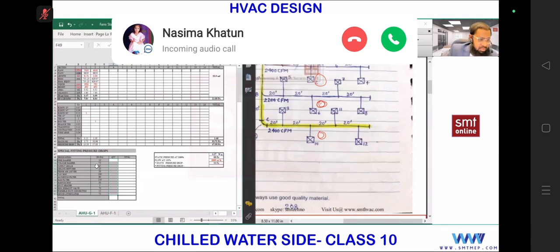For example, here in this project, I'm using this diffuser also there, no? Ceiling diffuser, one number, right? And say I'm considering one VAV box, for example, and one VCD also, volume damper. So enter the quantity, automatically get this value, these predefined values. So when you enter this, automatically at the end you will get the total pressure drop.